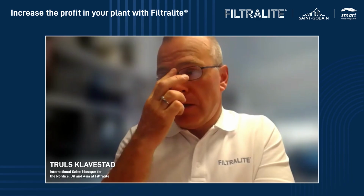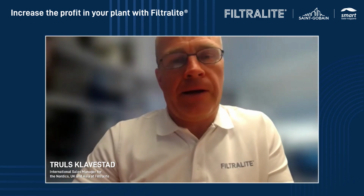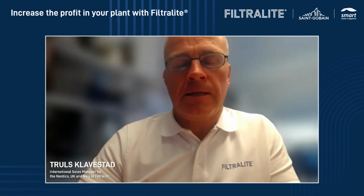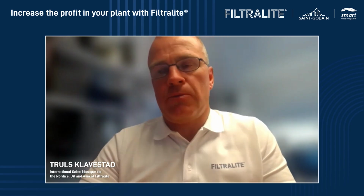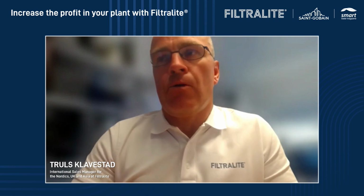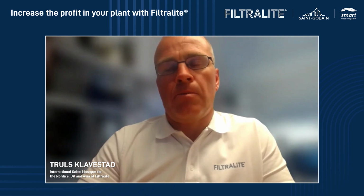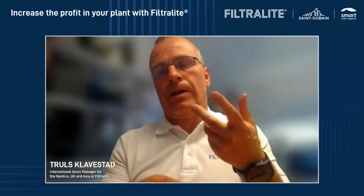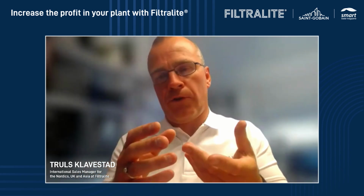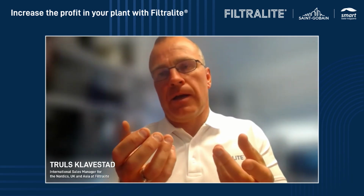We know that anthracite is a much softer material than Filtralite. When you have an application where you're using sand in combination with anthracite in a filter, and you backwash with a combination of air and water, the sand will polish the anthracite.